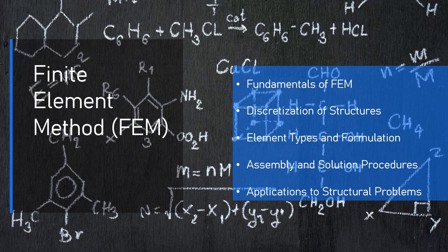The results are analyzed to check whether the stresses, displacements, or strains exceed acceptable limits. This is important for design and safety considerations. Stress analysis. Check if the stress in any part of the structure exceeds the material's yield or ultimate strength. Deflection limits. Ensure the displacements are within permissible limits based on design codes or safety requirements.